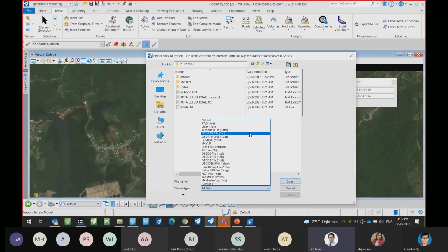Okay. Back to Mamat Haslami again. I think it's a clarification. He's asking how can I use Bing Map that show just as terrain model for the design alignment? The Bing map is used just as a reference in order for you to know if your project is in the right location, right?